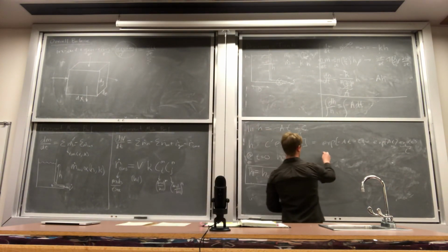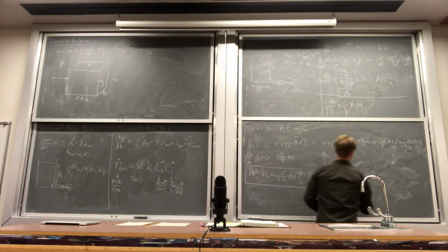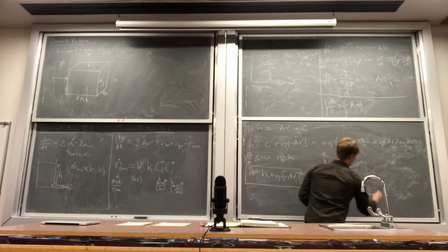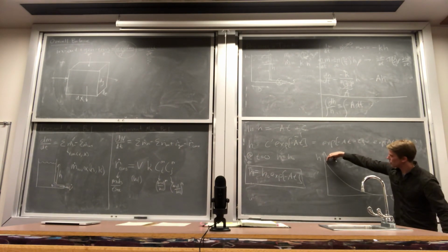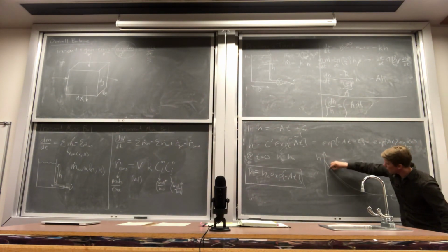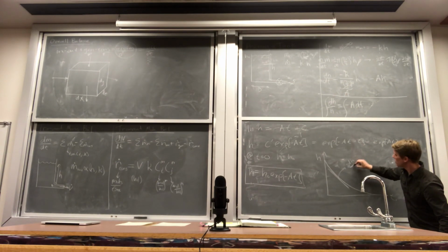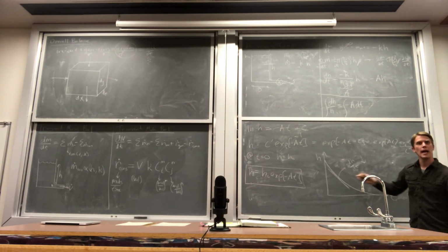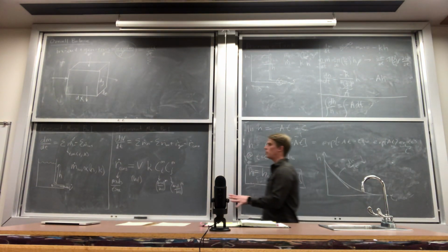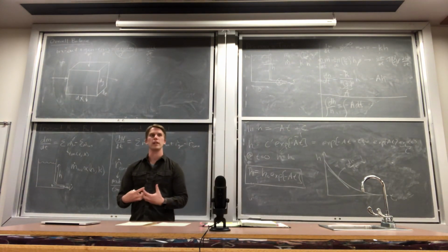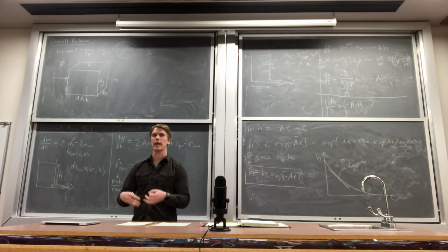So if we were to plot this out just quickly before everyone runs off, it is just a decay. So the h as a function of time. As the tank gets lower, the rate of change, dh dt, gets smaller as time progresses and the tank level gets lower and lower and lower. So what we're going to be doing for the next couple weeks in the class is basically deriving a lot of the expressions that you may see going forward and showing how the content and the transient level really applies to the fundamentals of chemical engineering throughout.